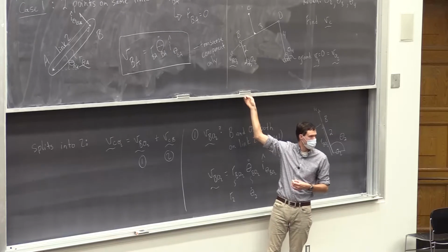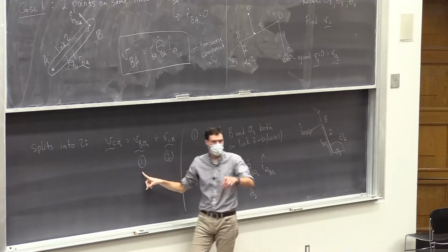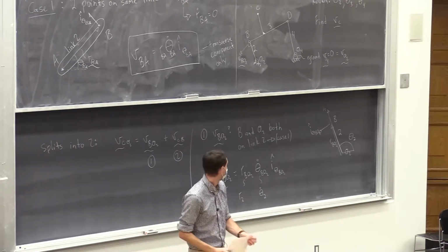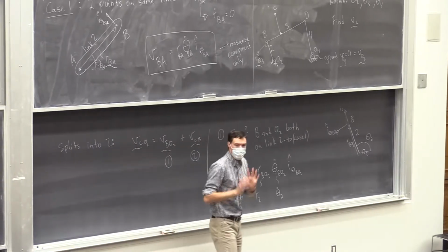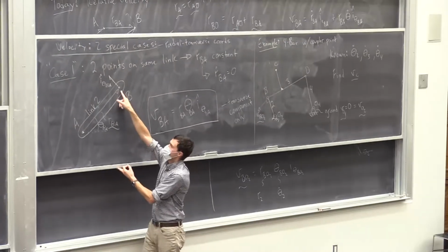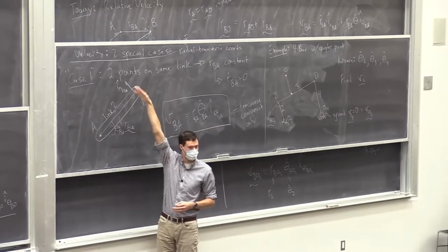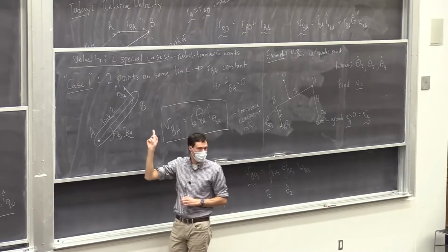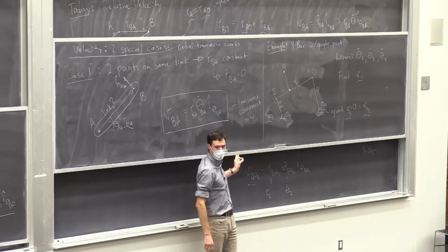Okay, any questions about this? It's our first velocity piece. Step 1, yeah. So like, in case 1, the velocities of points are always perpendicular to the radius? Yes, case 1, you choose your 2 points, connect them with that vector, and go perpendicular, counterclockwise. It's always going to be like that, regardless of the link shape. Our next link, link 3, is a weird shape, so we'll see what happens there.